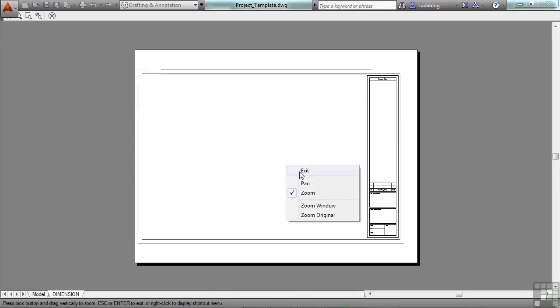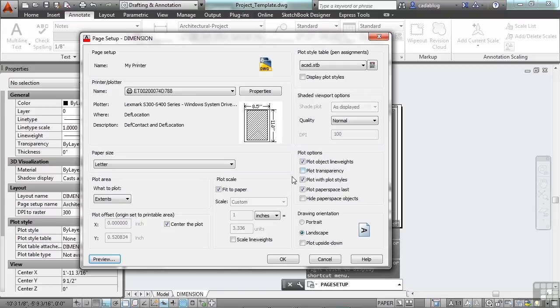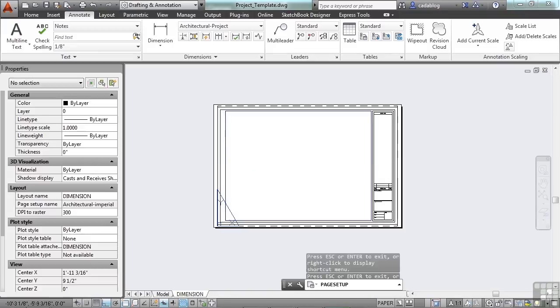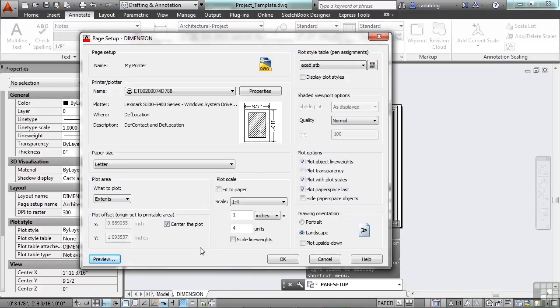It's not a perfect scale factor whatsoever. I admit that. But for what we're doing, it's okay. I can click on this fit to paper and then put in a scale, say 4. That will fit, as you can see on my preview. And it's a good scale that I can use, a factor of 4. So I can now put a scale on my drawing and scale some things, though I'm probably not going to want to because this is a real big reduction in size. It's a reduction of 4, 25%. So it makes it difficult. But that's okay. For what we want to do, I just want to show you how to do this and some things that you can do. And this is going to work.